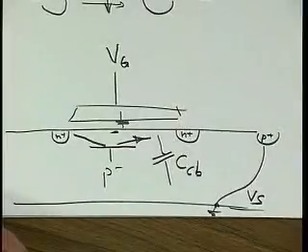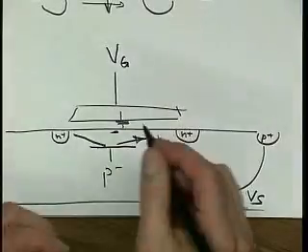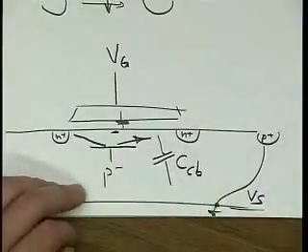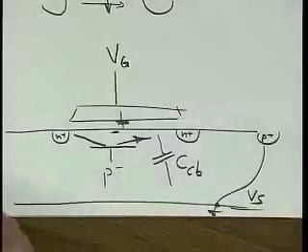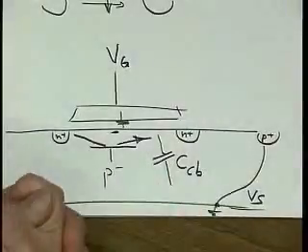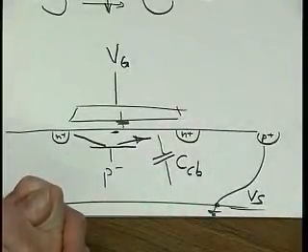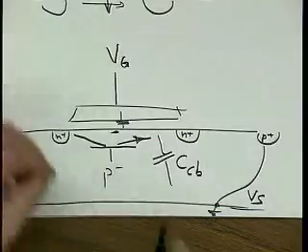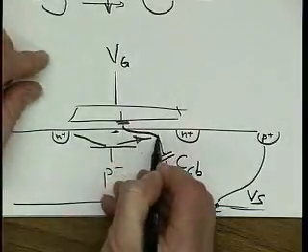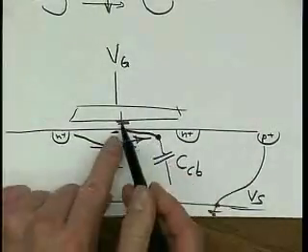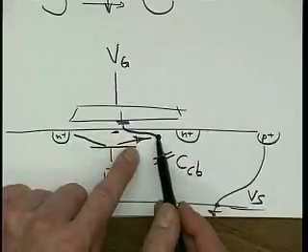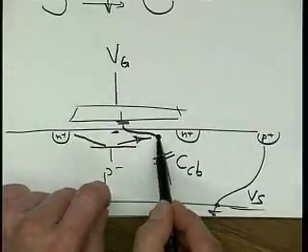Now, of course, there ought to be a penalty for not just setting the potential of the base, but going through this capacitive connection. And in fact, we ought to have capacitive division between this capacitor and this capacitor to this voltage here. That is really the base voltage.